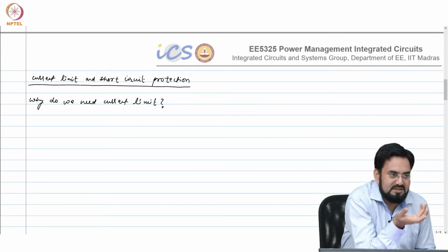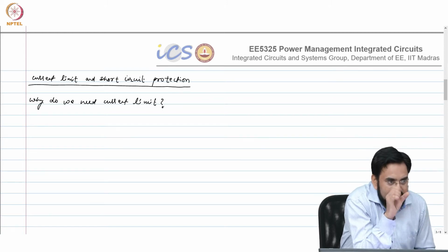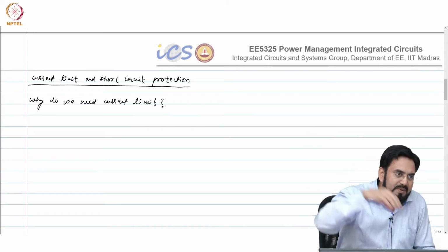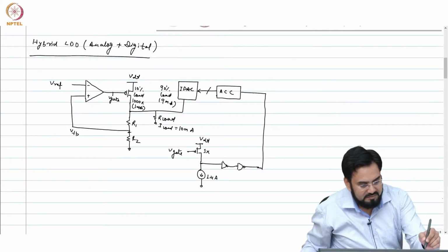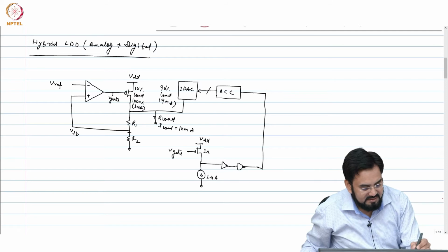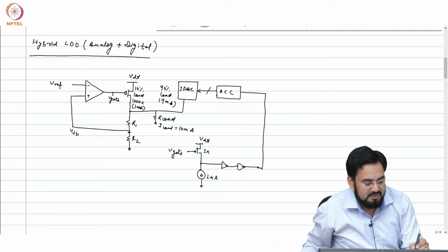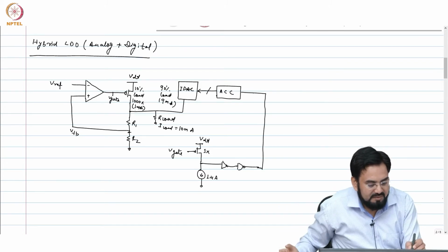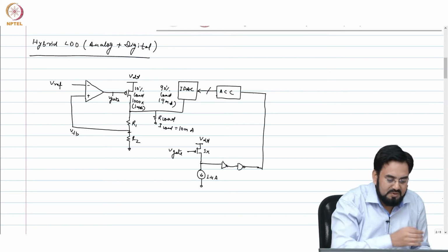It may even damage the source or drain of the device. Because usually when you do the layout, you route and put the metal traces that connect with the pad, so basically this drain. This is a drain which is connected to the load. So this drain is routed through a wide metal, and usually the width of that metal is defined.